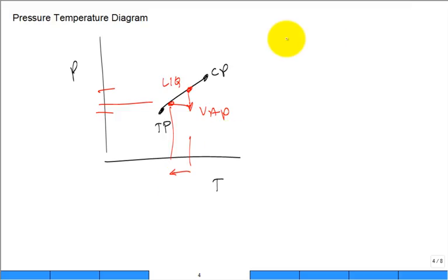So when we put it through the expansion valve, you can think about roughly 1/3 of it, quote unquote, flashes. What do you mean by flashes? It promptly goes into the vapor state. It took some energy to make it go into the vapor state. Basically, all of it's at the lower temperature, but 2/3 had a significant reduction in the temperature of that liquid. So there you go. That's the best I can do. You have to think about it. You have all the tools to explain it.